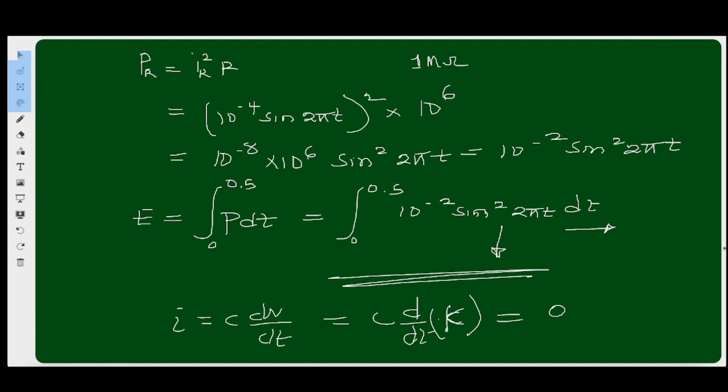This is very, very easy to understand. A capacitor will resist an abrupt change in its voltage. That is, at a particular point, let's say t is equal to 0, the value just before t gets to 0 and the value just after t passes 0 will be equal.